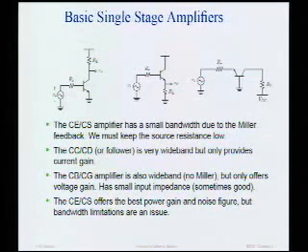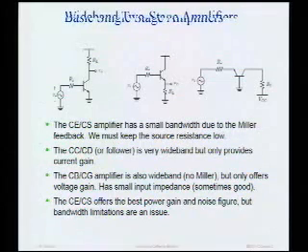In other words, when we have 2 stages or 3 stages, or if we use feedback. As we'll also learn later in this course, the common source amplifier is actually probably the best amplifier, not only in terms of power gain, but also in terms of noise performance. So if we're trying to design an amplifier that has a very low noise figure, this is the topology of choice. So all we need to do is somehow fix this and make it more robust.